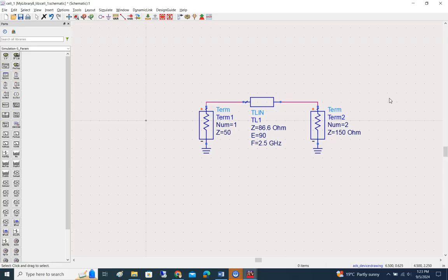I'm not sure whether you have heard about the S parameter, the transmission coefficient or reflection coefficient in terms of amplitude. These are really important parameters whenever we are designing any RF systems, RF components or antennas. So we have to put ports at both ends. Let's put port one this side and port two that side to measure the S parameter and other things.